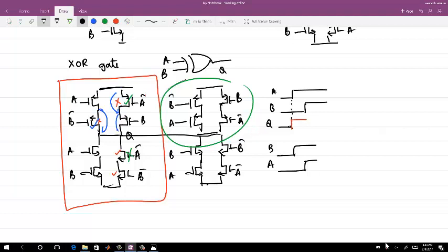It is putting more load on the, not necessarily. So why would I, if I have an X circuit, always do X and X? I can do X by 2 and X by 2. Whether it is going to put more load on the previous stage actually depends on how you do it. Now the whole question is you may have more intermediate nodes, but those intermediate nodes are also having lesser capacitance.